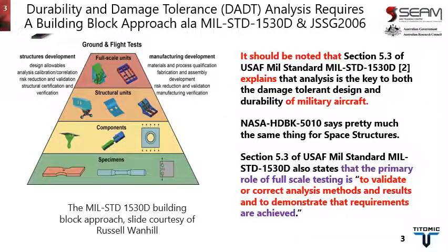The durability and damage tolerance, or DADT analysis, requires a building block approach as spelled out in Mil Standard 1530D and JSSG 2006. However, Section 5.3 of Mil Standard 1530D explains that analysis is the key to both the damage tolerance and the durability of military airplanes. NASA Handbook 5010 says pretty much the same thing for space structures. Section 5.3 of the Mil Standard also states that the primary role of full-scale testing is to validate correct analysis methods.